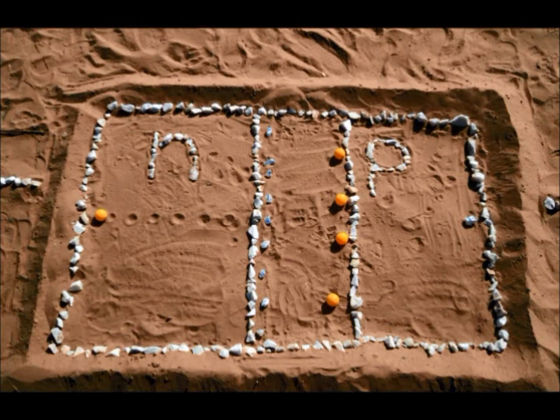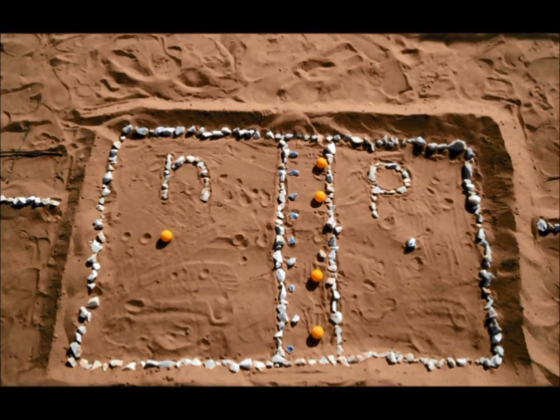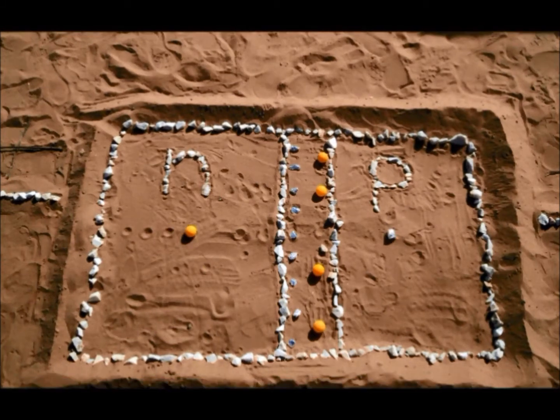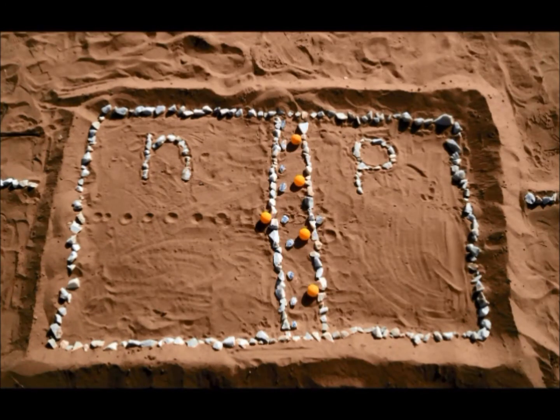To understand the applications of diodes, let us first have a look at the basic working of a diode, which involves forward and reverse bias. In forward bias, positive potential at P repels holes and the negative potential at N repels electrons towards the junction, which in turn makes the diode conduct electricity.